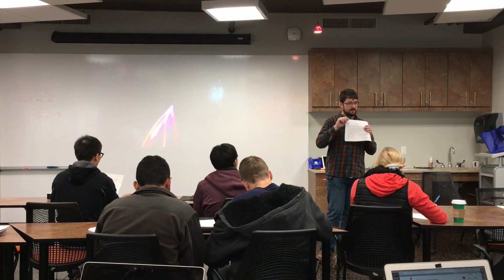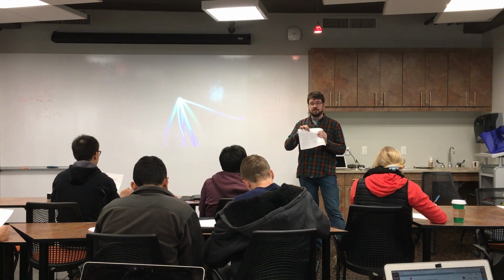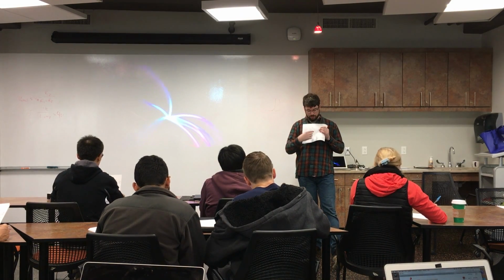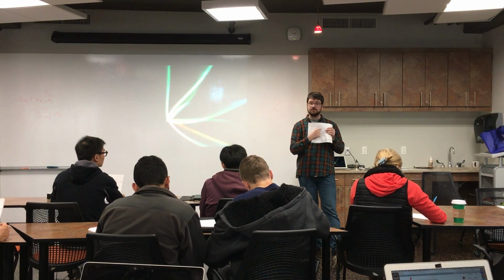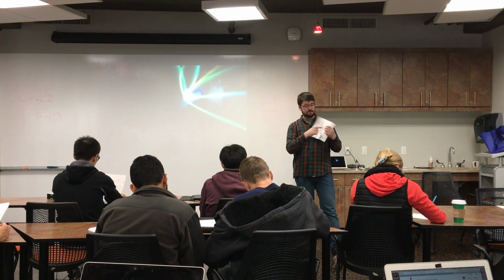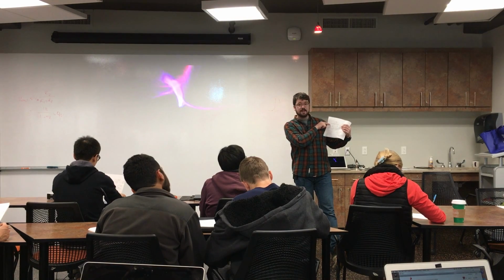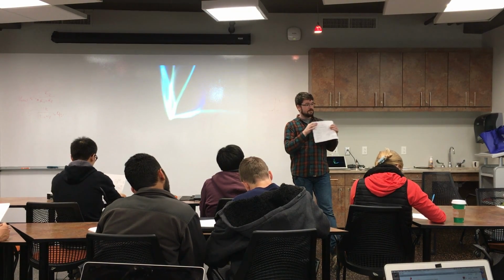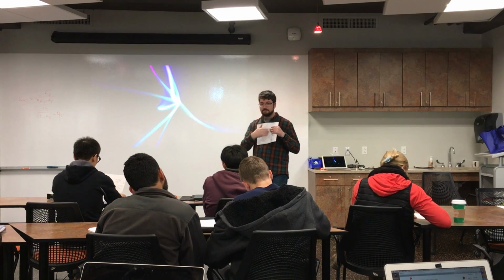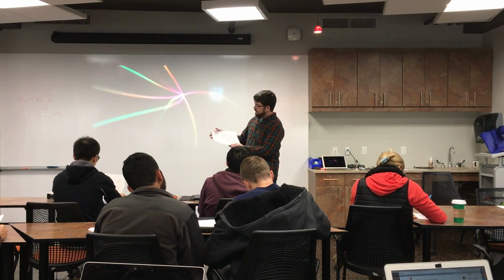This is a 10-turn potentiometer in real life, so you have very fine control over that range of voltages. Then you can flip the switch and have very fine control over the next range, all the way up to the plus rail and the minus rail. So it's just a switched voltage divider and a potentiometer. So lots of voltage divider math.